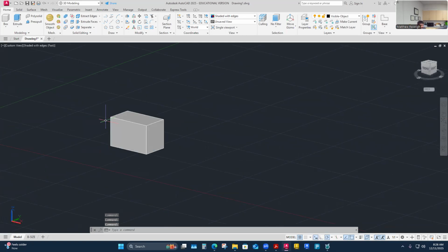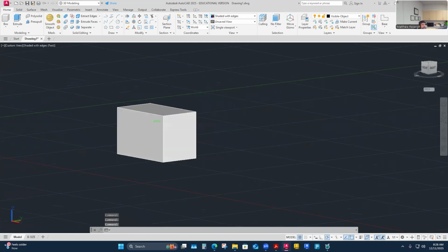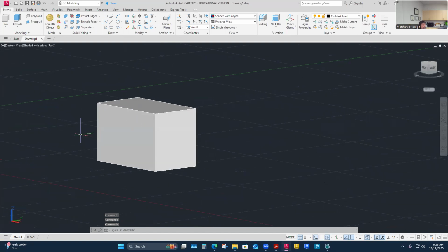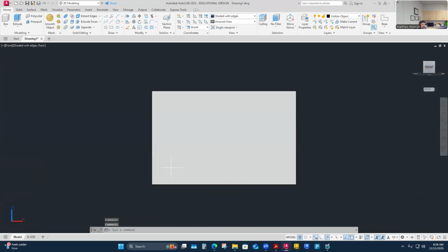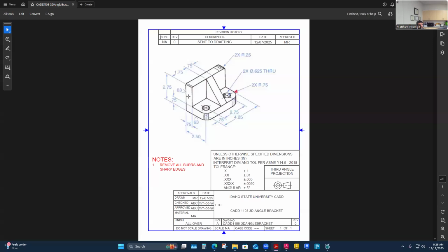So we'll do some subtractive cutting here now. A lot of different ways you can do that too. I'll just do a sketch and press pull them, I think is what I'll do. Sketch them. You're just going to draw it how it's shown. Yeah, well, this is my front view right here, so it's going to be 4.25 by 2.75. So I'm slightly orienting it differently. I always feel like these views are driving me towards this being kind of front and right side, but I'm going to choose this as front, and the back side is right side.